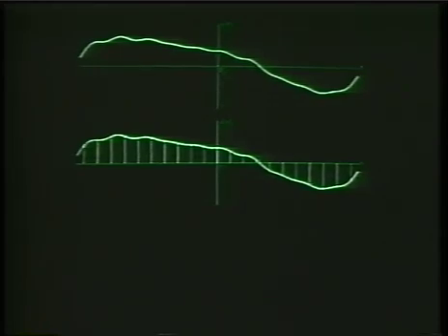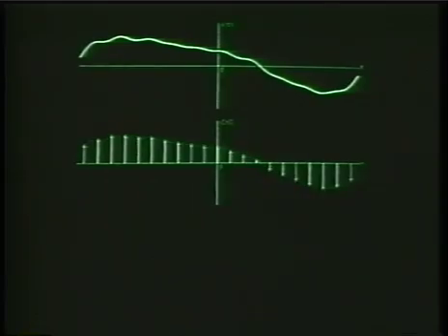Well, let's remove that envelope so that we focus attention on the samples that we're using to interpolate. And the interpolation process consists of replacing each sample by a rectangular signal whose amplitude is equal to the sample size. So let's put one, first of all, at t equals 0 associated with that sample. And that then would be the interpolating rectangle associated with the sample at t equals 0.